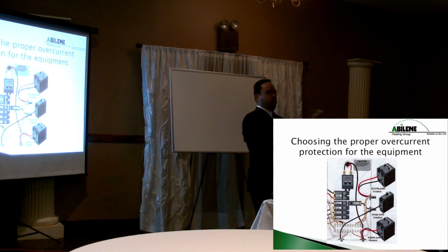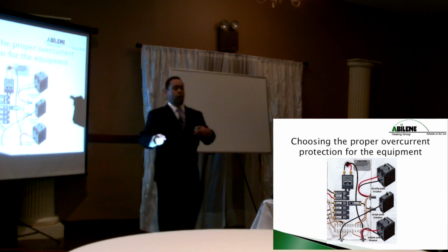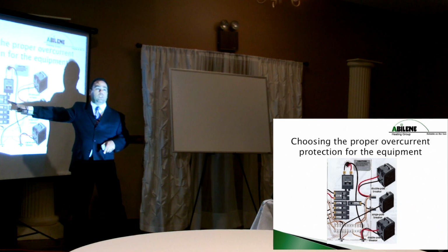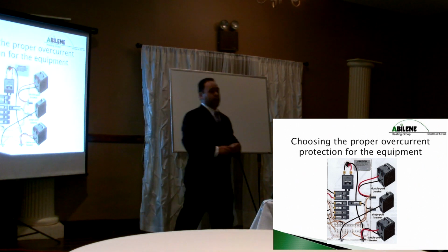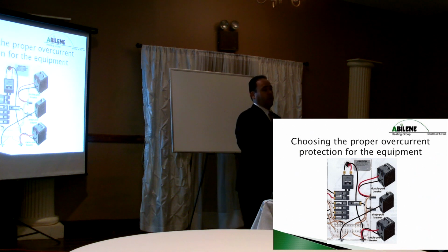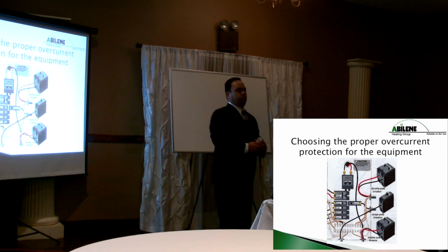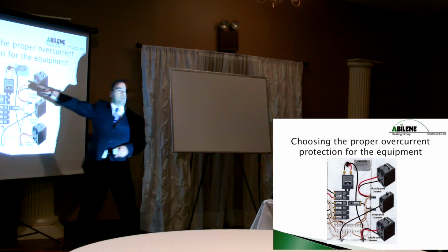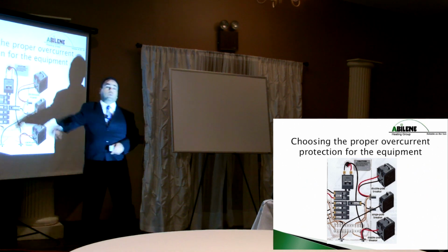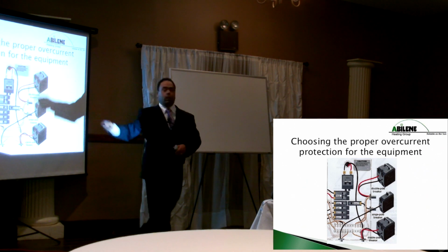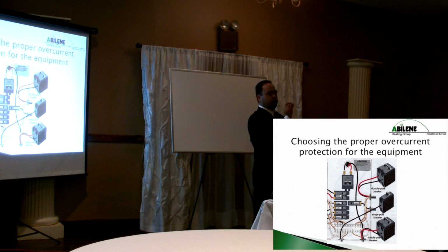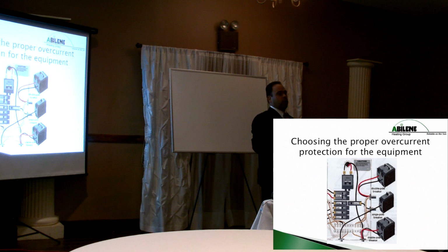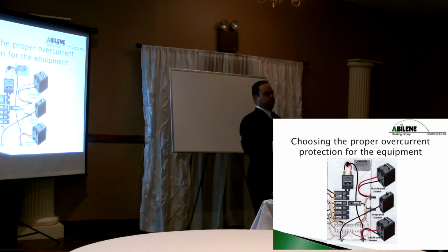Because a lot of people are just buying breakers. Now, on overcurrent or draw, this one is going to trip first. But on a dead short, that's where you're getting that breaker tripping first, because on short current, it's got a lower rating than that one. You look at the side of the breaker, it'll tell you what the short current ampacity is.